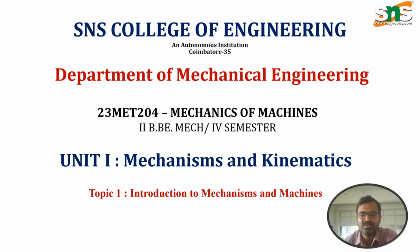Today, I am going to discuss a new topic related to the introduction to mechanisms and machines. First of all, what is meant by mechanisms? If we take a single machine, combinations of different mechanisms are incorporated into that machine. For example, take the lathe. We use a lead screw. What is the purpose of using a lead screw? It converts rotary motion into linear motion. So different kinds of mechanisms are incorporated in machines.